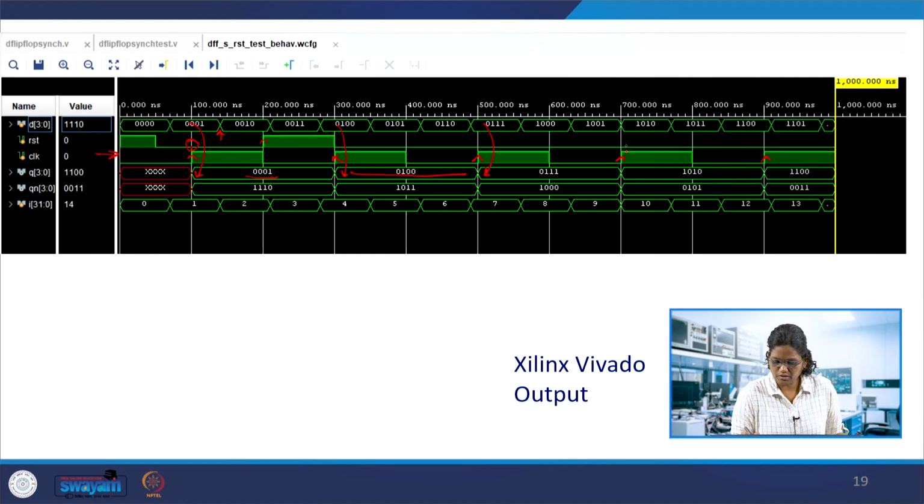And at this clock edge, this is exact data change, but this should not occur in real time, when we consider timing. There should be a setup and hold violation if we do that. So in making it 1 0 1 0, at this point the data is 1 1 0, so that is also getting into the Q.